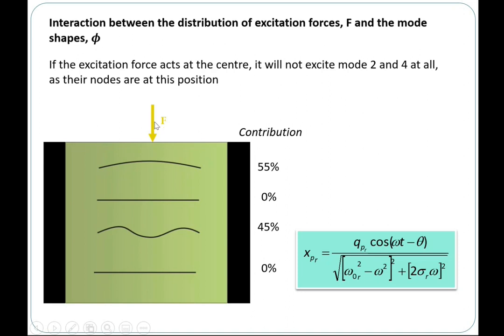So if I act here with my nodal force, with an excitation frequency near omega 2, by right you should have resonance. But in that case, because the place where you put your force is at the nodal point of mode 2, even if omega naught 1 and omega naught 2 are exactly the same and cancel out, even with no damping, you won't have resonance.